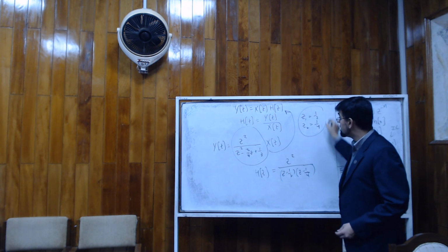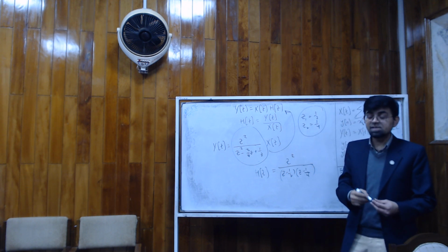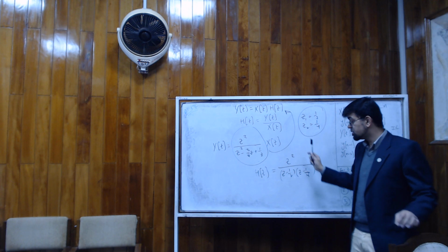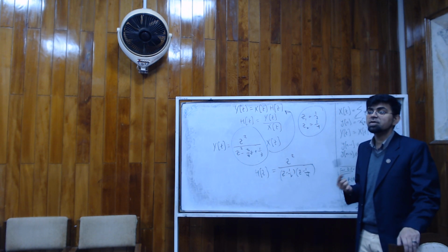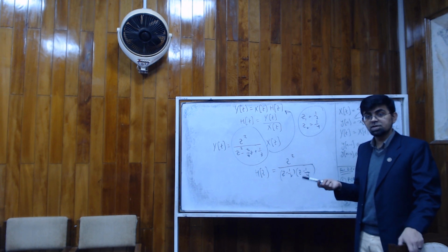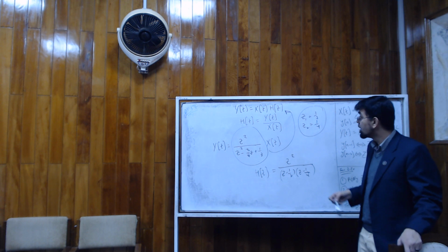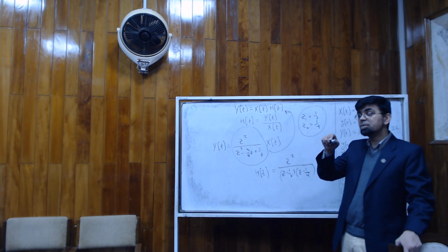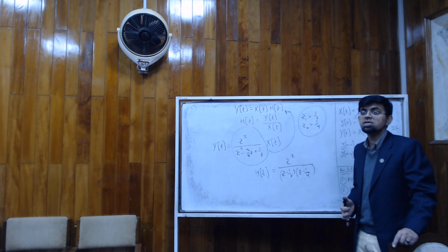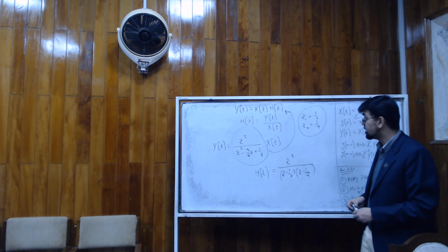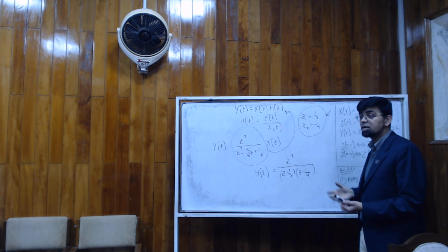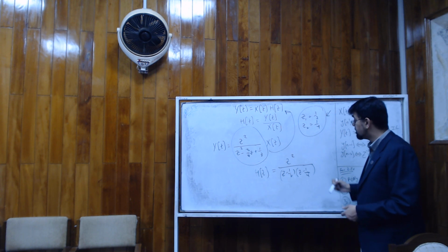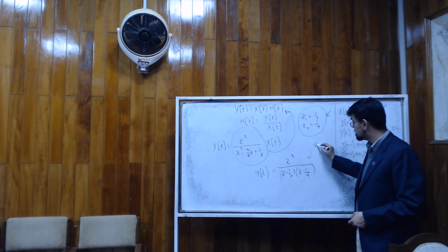Yes. Now for a dt, so the poles, let's say let's call that z1, first pole, and second pole is 1 by 4. A discrete time LTI system is stable if the poles of its transfer function are where? Left half plane or inside the unit circle? Inside. Inside the unit circle. We have done this also. For Laplace transform, it's where is it? For continuous time, it has to be in the left half plane. Now these poles, are they inside the unit circle? Yes. They are less than 1. Yes. So this system is stable.